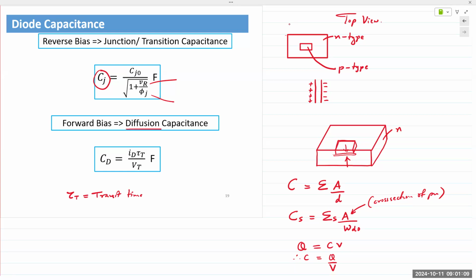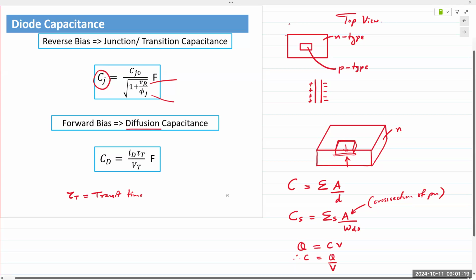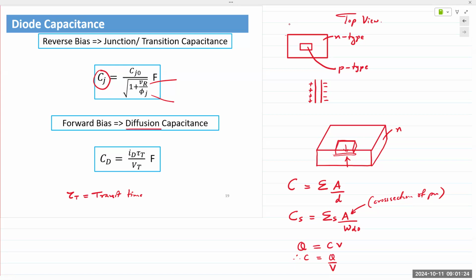So the reverse also occurs. Electron can move into an empty spot. That process is known as recombination. So it's known as the minority carrier lifetime. Okay, so it's a transit time, minority carrier lifetime. How long before that electron will fill up a hole? It's typically 10 raised to minus 15 seconds. Okay, femtoseconds or smaller.